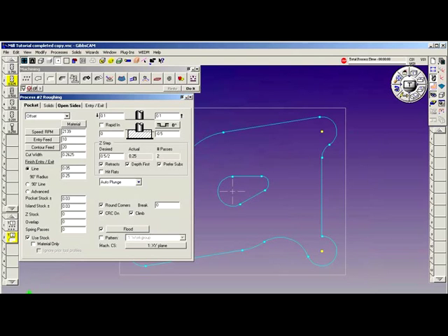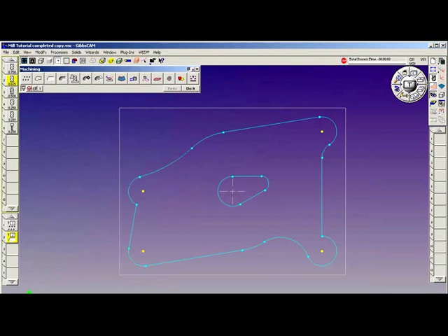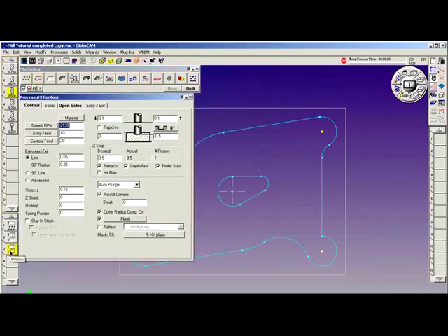All right, so we'll go ahead and we'll close out the roughing process. And we're going to stack one more tool on this process, and this is going to be the finish tool. This is tool number 3. Tool number 3 is going to be a contour cut. We're going to finish the ID of the pocket and the OD of that island with this particular cutter.